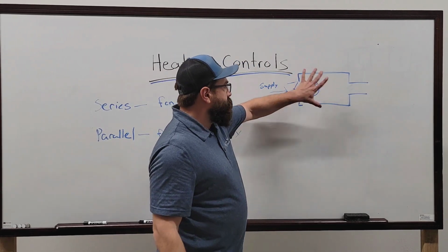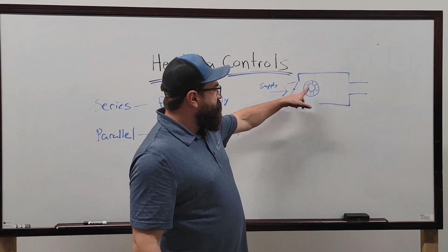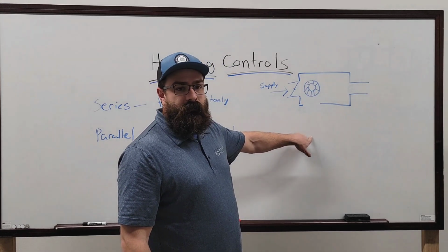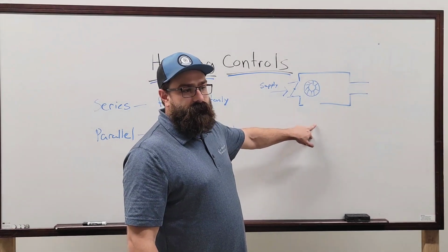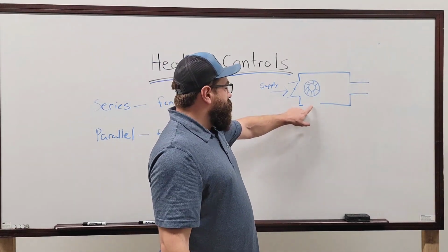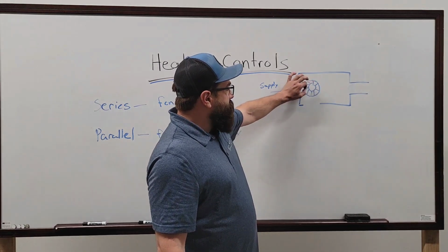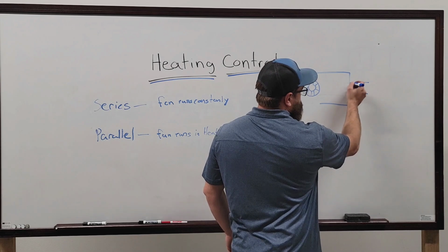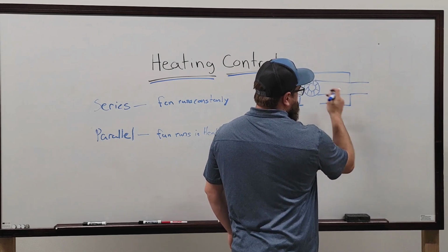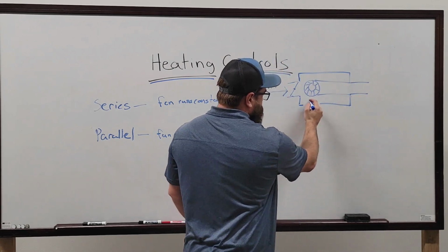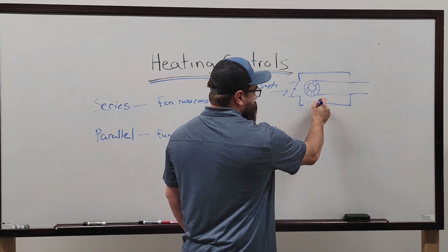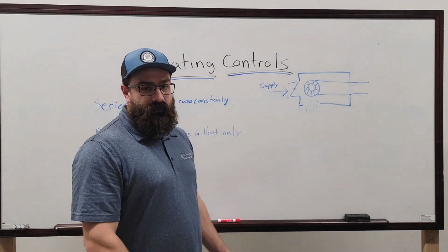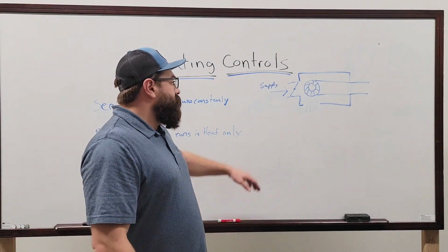Air comes into the supply duct and pressurizes the cabinet. If the fan is not running, everything will escape from the side pocket, or the return, whatever you want to call it. It has to pass through the fan to get pushed out of the box. If the fan's not running, you'll see a lot of air coming out of that side grill, pocket, box, whatever you want to call it, on the unit.